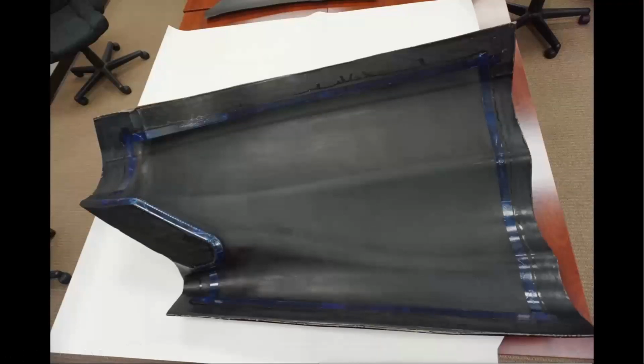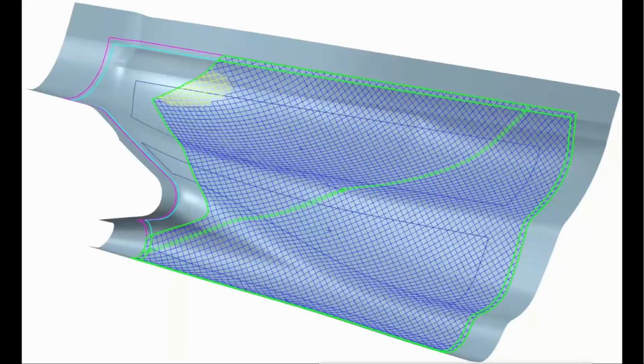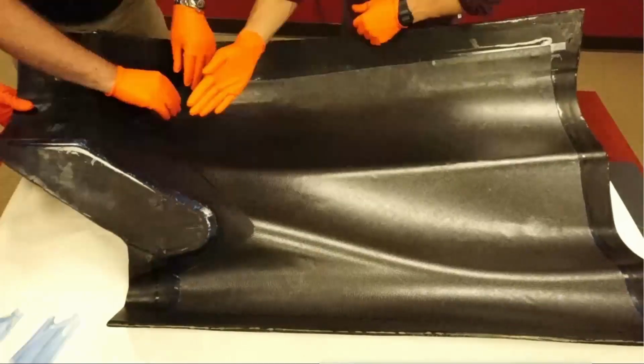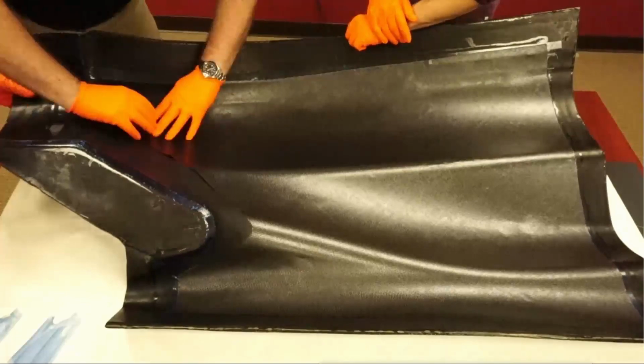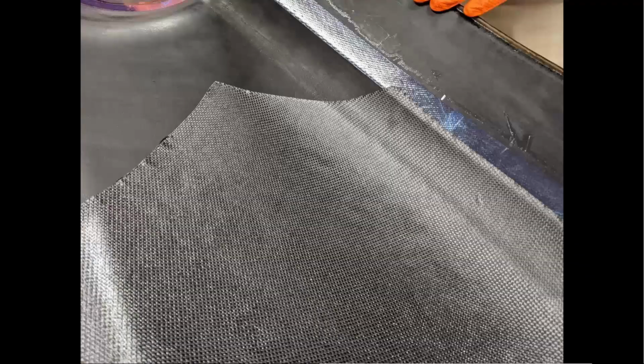So P1A is going to be the larger ply you see in a second. It's a very large one on the right. P1B is that forward one. P1C is in the center. These are the simulation results, and you see that area in yellow. That requires that the technicians smooth that material and work it a little bit. So they're going to have to deform the normally orthogonal fiber cells, but it does lay into the tool, and it lays out exactly as shown in Fibersim.